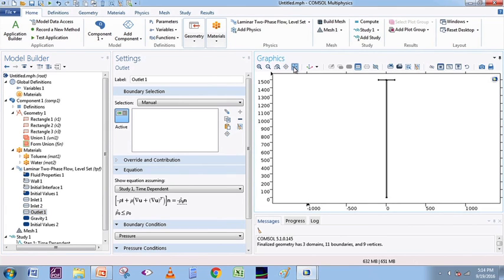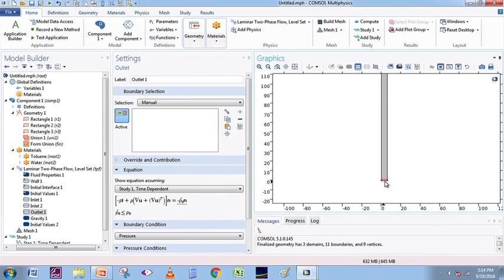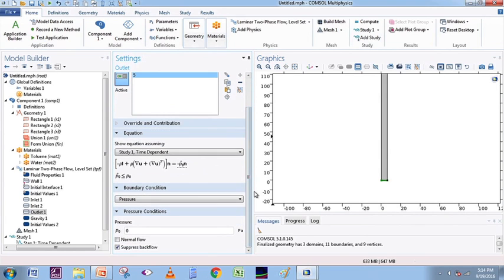Now, we need to specify our outlet condition, the discharge will be at atmospheric pressure. Again click on zoom extents and go for enlarging my outlet, and I select this is my outlet. It automatically gets added when I click on it. Then there are various options: velocity, pressure, laminar outflow. I select pressure outlet and I type in 101,325 Pascal. During experimental condition no backflow was observed.